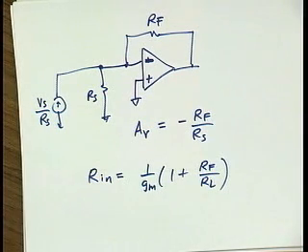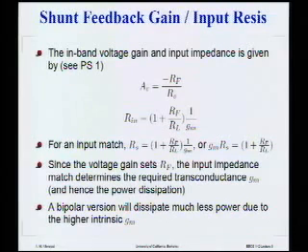Coming back to the slide, we can see that to obtain an input impedance match, we set gm·RS equal to 1 plus RF over RL. Usually, because the gain is really set by RF, and I say that because in most cases RS is fixed. It's something that you have to work with.